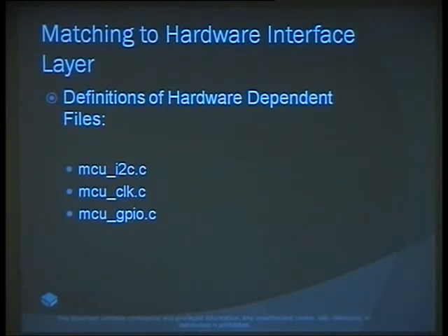So you are trying to modularize your code so that when you are making your code, you don't have to worry about peripherals, configuration of the peripherals. You don't have to worry about activation of the peripherals. That's why it becomes easier when you're developing complex code. The memory required for this kind of code is a little bit higher. If you do everything in assembly, of course, you'll have better code efficiency and optimization. In this case, you're going to have a little bit more overhead. Definitely, when you go for a high-level language, you get that trouble.